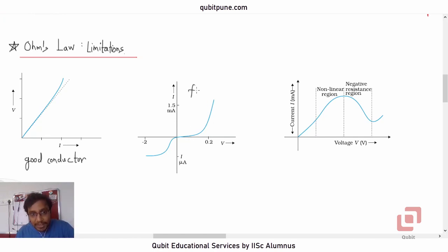In the forward bias condition, after overcoming the barrier potential, also sometimes called the knee, if you remember, and the corresponding value is called the barrier potential. After this, the current almost varies linearly with voltage. So this is the ohmic behavior of the PN junction diode.